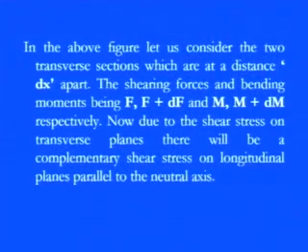which are a distance of delta x apart from one point to another point. The shearing forces and the bending moment, as we discussed: at one point it is F in this direction, and at another point we have F plus dF in this direction. Then we have the bending moment also: at one point it is M, going in this direction, and M plus dM, going in this direction. So both sides are being influenced by both shear forces as well as the bending moment.